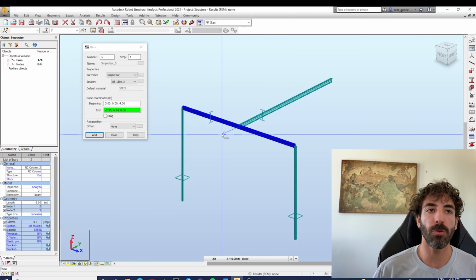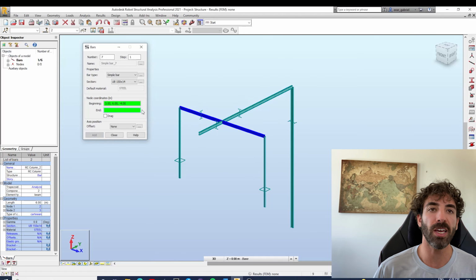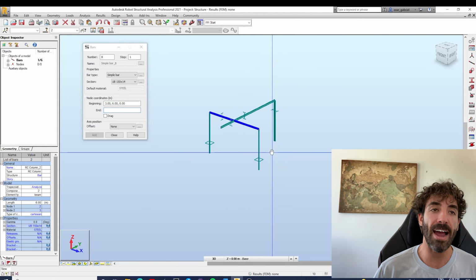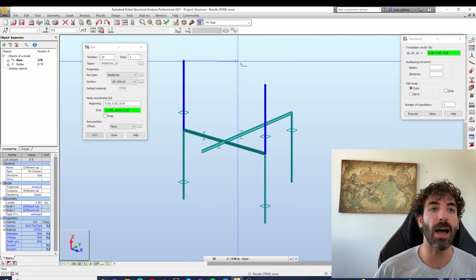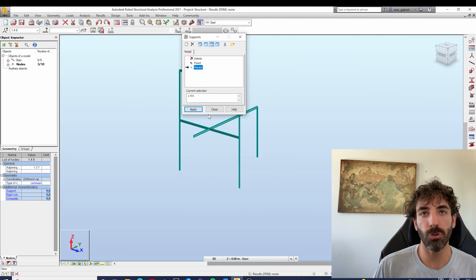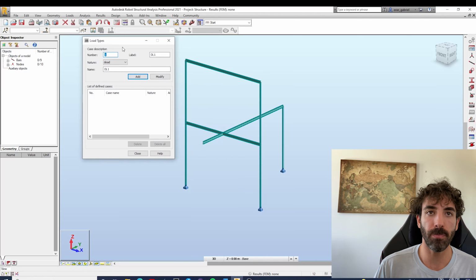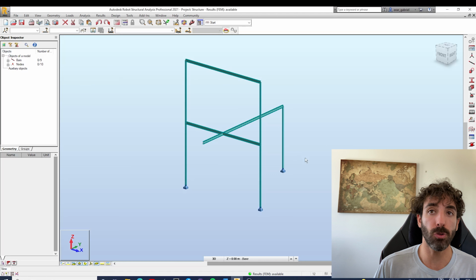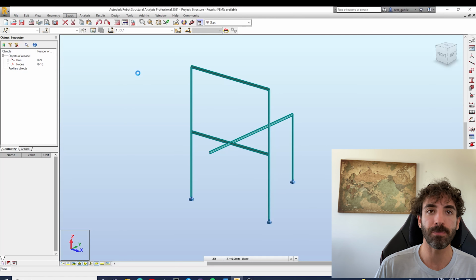We're going to look at global deflection and local deflection, and I'll show you some steps to make sure your 3D model will accurately represent what's going to be built in real life. To start with, I just wanted to remind you to not forget to add the self-weight of the structure. I'm just saying that because some software will not add the self-weight automatically, and it's easy to miss this step.